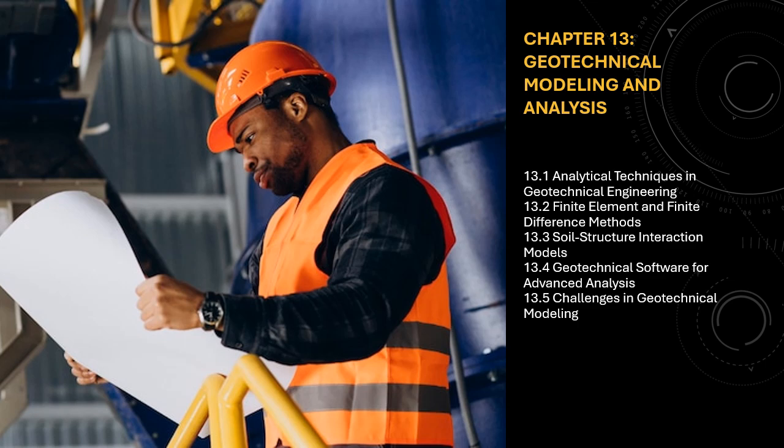13.1.4.1 Linear SSI models. In linear soil structure interaction models, the soil is treated as a linear elastic medium, and the structure's response to seismic or static loading is computed. These models are suitable for problems where soil behavior is predominantly elastic.